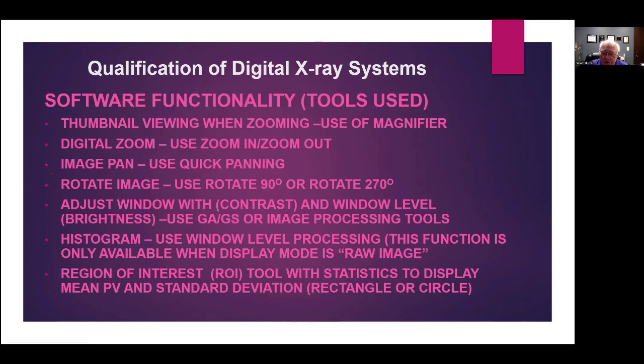Then there's a lot of tools involved in digital radiography, and a lot of the system performance asks that you qualify or demonstrate the ability to use all these different tools. Now, some of these are within the ASTM documents. A lot of them are in customer documents and or quote NADCAP requirements from time to time. So there's a number of different tests. So thumbnail viewing, so you can go on your monitor, look at a specific part of the image and use this magnifier to zoom in on that area.